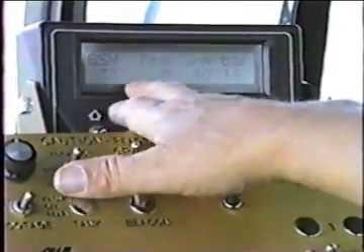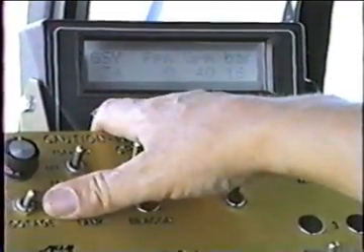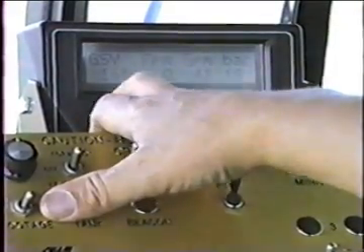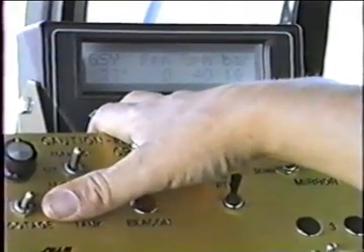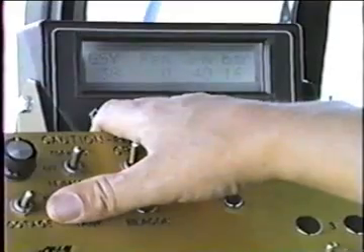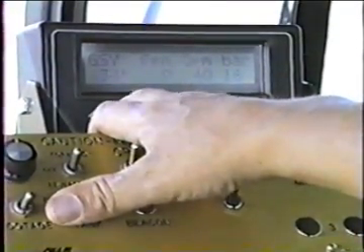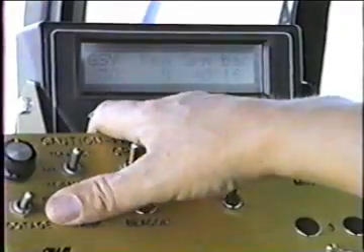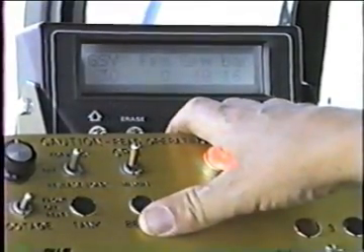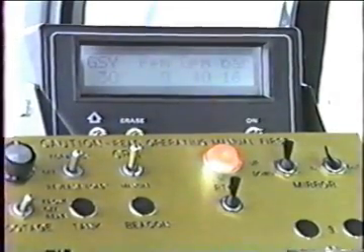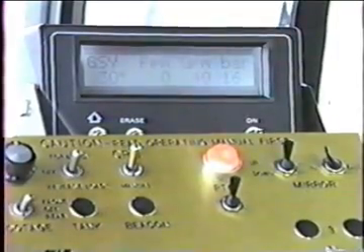To set the GSY, simply hold the switch down or hold it up to the number that you desire. Today, let's say that we're going to shoot 3/10 of a gallon to the yard. A single click is a single hundredth of a gallon. That takes us to 0.3. We've got 3/10 of a gallon set.